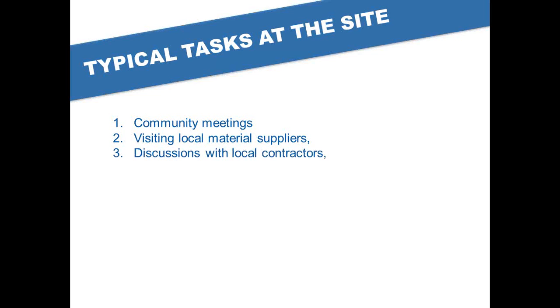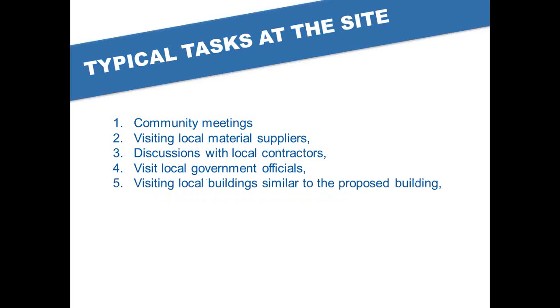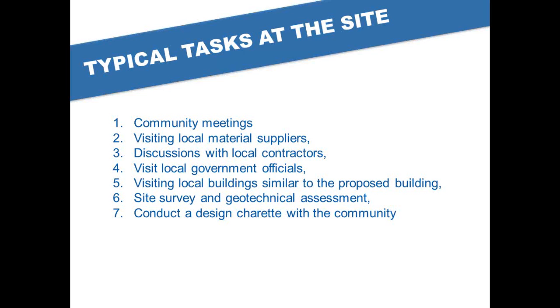You'll have discussions with local contractors about how you go about building stuff and what materials are available, what labor is available. You'll perhaps visit local government officials to see if there's any building permits required. You'll visit local buildings that are similar to your proposed building, to get the construction methodologies. You do a site survey and geotechnical assessment.